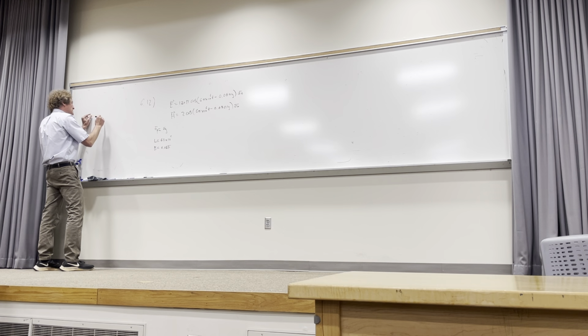You know that in general, gamma is equal to the square root of j omega mu times sigma plus j omega epsilon, right? And gamma is equal to alpha plus j beta, right? Are you all following me? I'm just putting out the reasoning behind it. Now, I know it's lossless, because sigma is 0, isn't it, class?